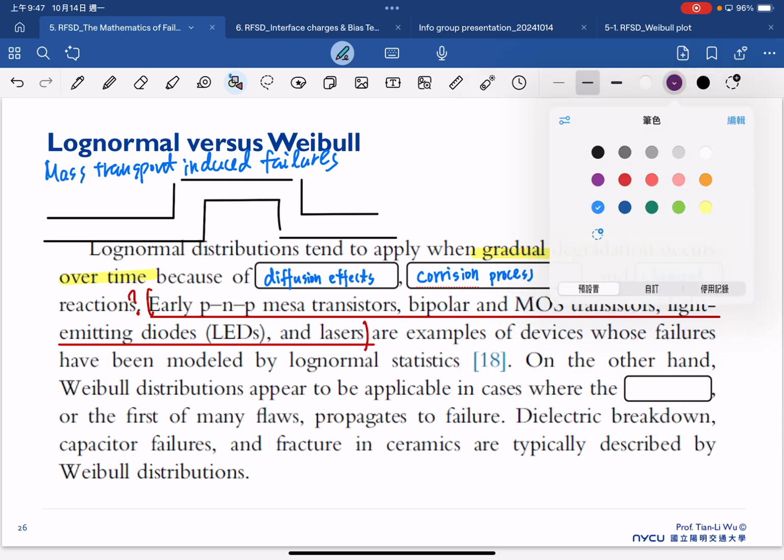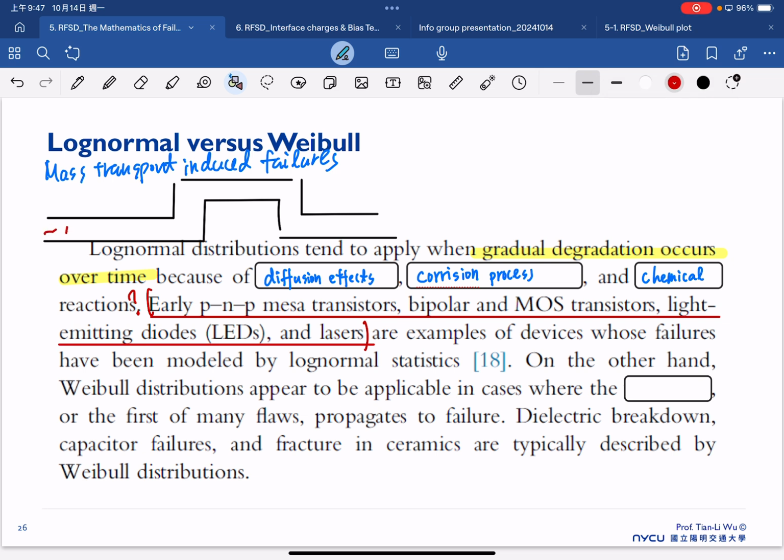So we have a huge amount of electrons flowing inside this interconnection line. And as we already mentioned in the previous introduction, the main concern for the interconnection line under high current operation is that these electrons provide a huge momentum to the atoms inside the interconnection line.